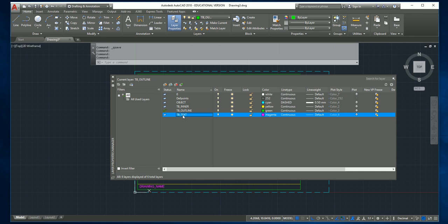So it's not gonna show in the layer property box. No. So how do we change the color in that? So you would create a new layer, call it TB text, then you come over and change the layer, and then change the object to that layer. Everybody able to create a new layer and move their attribute to the new layer? No, Connie? No?